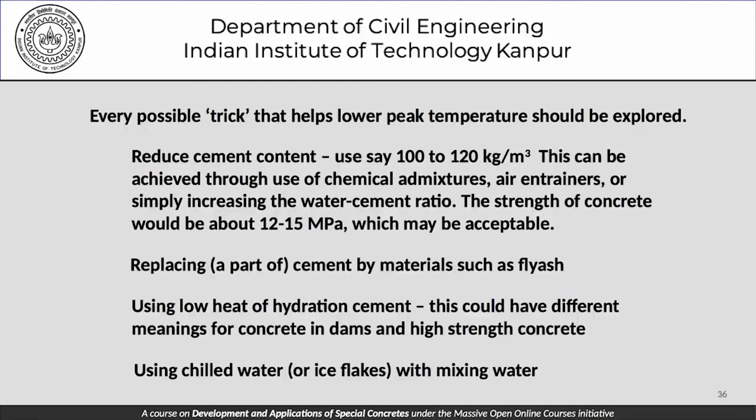Using low heat of hydration cement, this could have different meanings for concretes in dams and high strength concretes. Using chilled water with ice flakes as mixing water or with the mixing water to lower the temperature. Recall that we had prescribed a similar treatment when we were talking of a special condition of placement, hot weather and cold weather kind of concretes. There also we had suggested that if we want to reduce the temperature of concrete, use of chilled water would be one of the things that could be used.